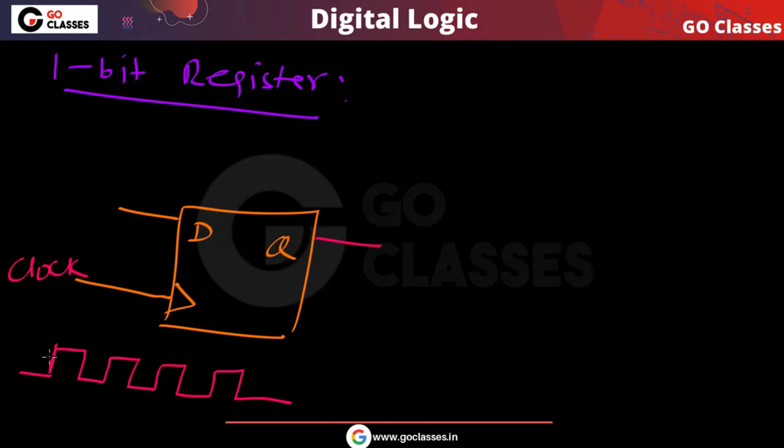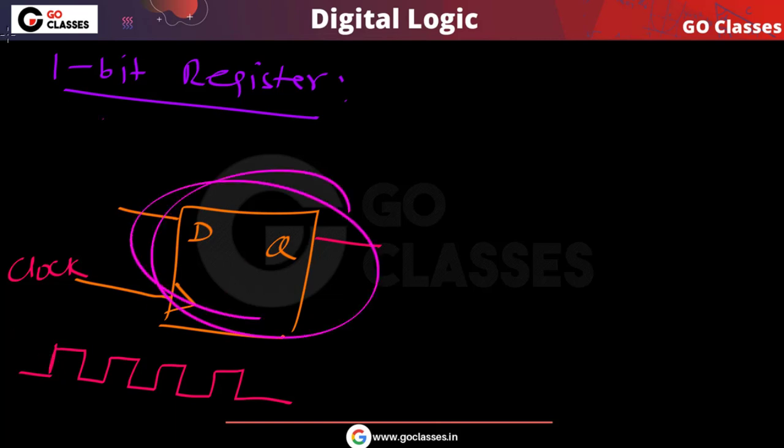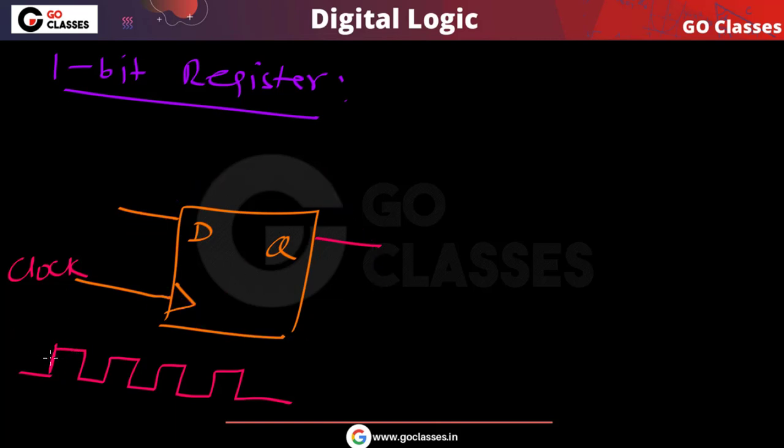Now you can notice this D flip flop is positive edge triggered. What does it mean? It means that whenever this clock goes from low to high, this flip flop will be triggered. Whenever the clock goes from low to high, then this input data will be available on the output. Now we need something called load, so that we can control when to store the data, when to change this output.